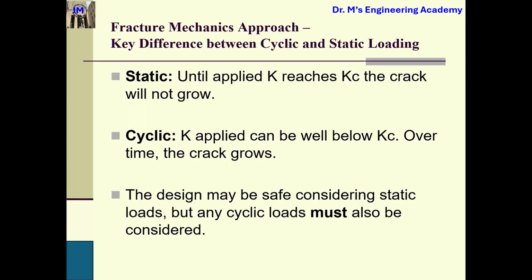Whether it is static loading only, or under some conditions this component or system will experience cyclic loading. If cyclic loading, you must consider fatigue, fatigue strength. You must be very careful. Otherwise, it will be very dangerous. Also, because cyclic loading always happens at a very low stress level, it is more dangerous than the static loading.